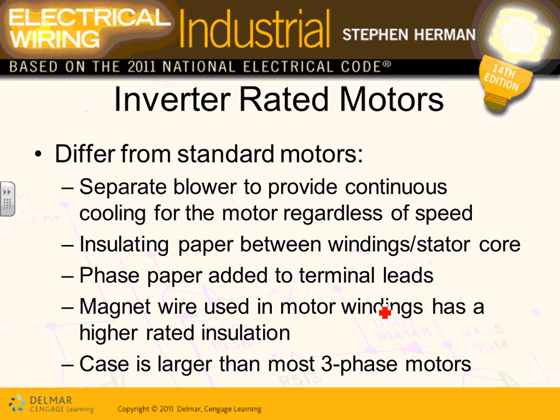Okay, so without getting too much into it, guys, VFDs, we specify them to control the speed of an AC induction motor. What they do is they take AC to DC and invert it back to some form of AC pulsation. Why do we do that? To control the speed of a motor. What's the impact? They create heat inside the motors. So Adam, you're going to hear people at Michelle Cooley Erickson and everywhere else talking about inverter-rated motors. You're going to hear them all the time, guys.